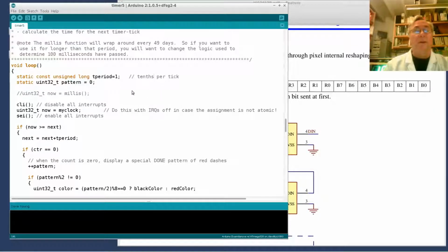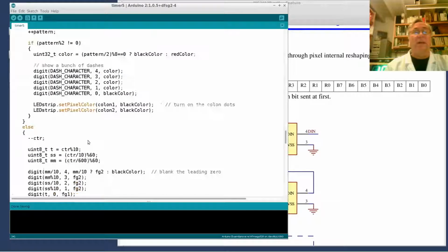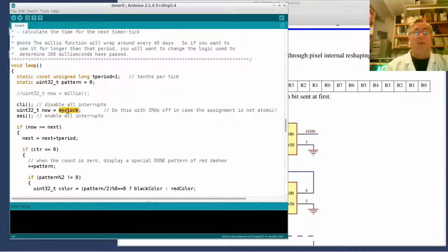All right. Now that's good. I got my own clock, and the rest of the code is the same as it ever was before. Now I can't miss interrupts because they don't happen as often, and this still takes the same amount of time, which is on the order of 8 or 9 milliseconds. This thing over here changes only once every 100 milliseconds, so I can't have that problem anymore. And now my clock will run at the right speed. Let's download this, make sure it works. Would be nice, always when demonstrating something. Hey, okay. So I'll push this up to GitHub. We're done.